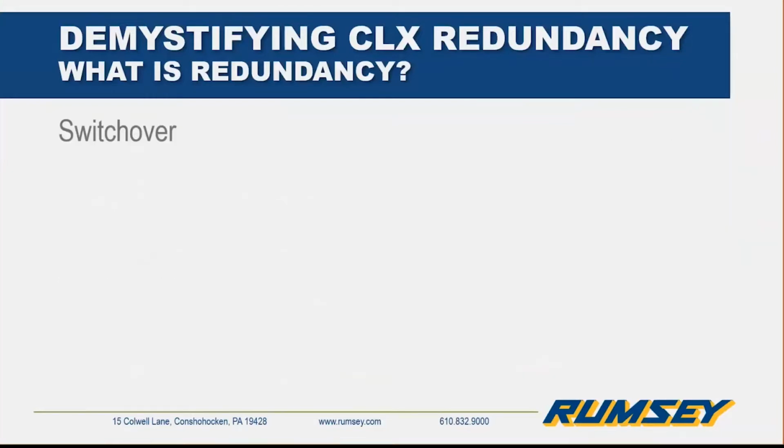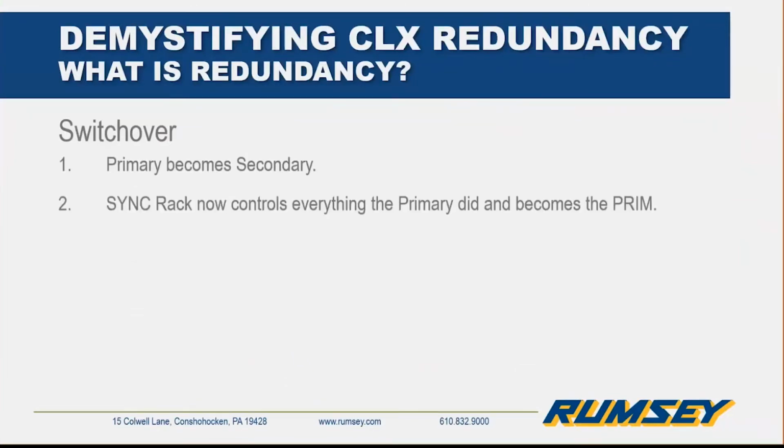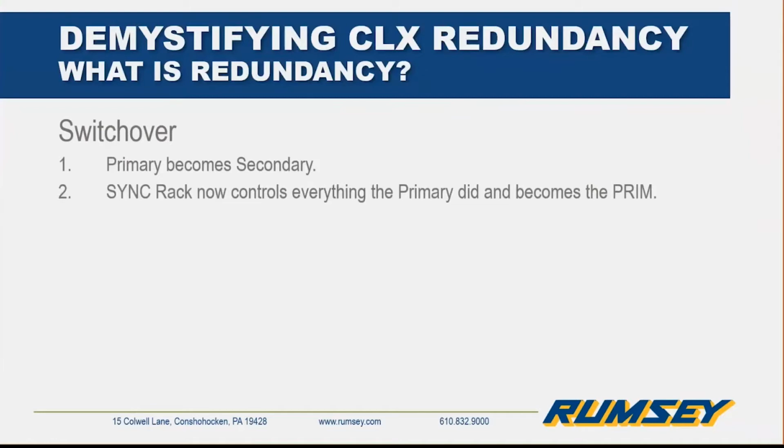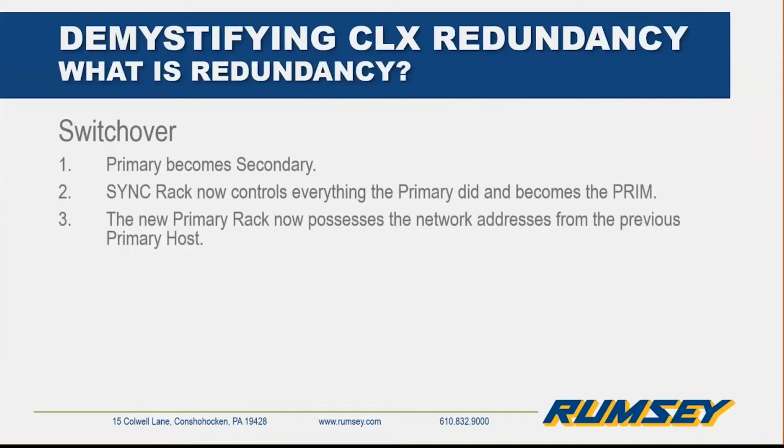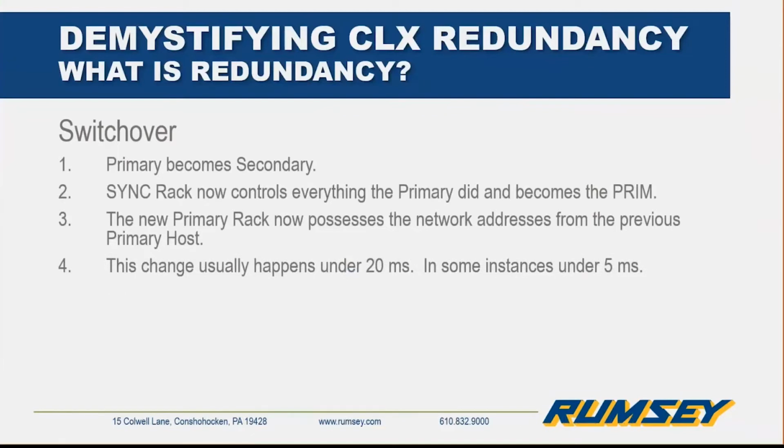All right, switchover. This is where the primary becomes the secondary. The sync rack now controls everything as the primary. The new primary rack now possesses those addresses. So that's why I was talking about the flipping of the addresses. It's instant. When this happens, again, it's usually under 20. I've seen many cases under 5.